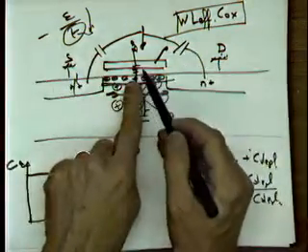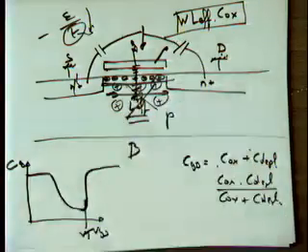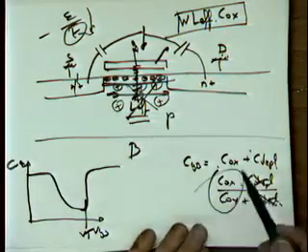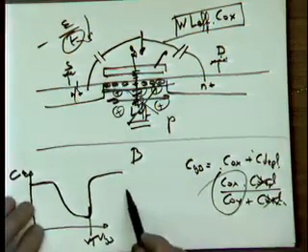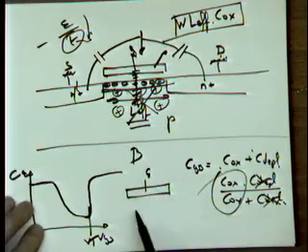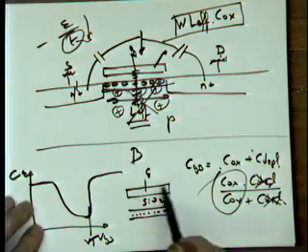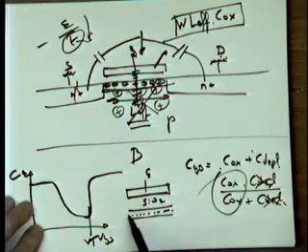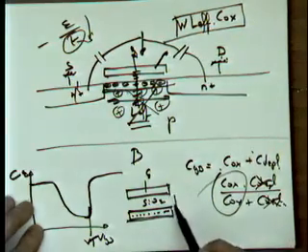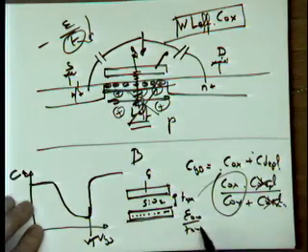So we look at the capacitance now between the channel and the gate: it is WL times Cox. The depletion cap is gone, we don't worry about this anymore. We're back to the Cox value. Well, if it's a conductor, it's like a capacitor with zero capacitance, isn't it? No, so you have the gate here, you have silicon dioxide, and I have my channel. What I have now is a capacitor that has on one side a polysilicon conductor, on the other side the channel as a conductor, and in between a dielectric material with a thickness equal to Tox. So the capacitance here that I see is epsilon ox over Tox times W times L.